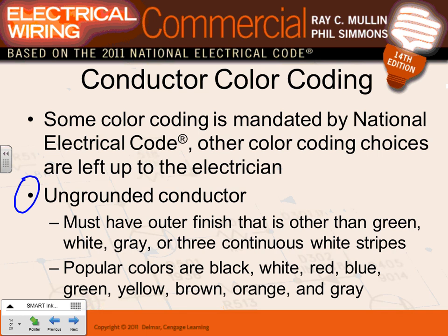Can you guys go to page 102, please? In your book, page 102. On the left-hand side, they give you the industry standard color coding for your system. So we have single phase 2-wire: black, white. 120/240 single phase in a conduit, 3-wire: black, white, and red. 208/120 three phase, 4-wire: black, white, red, blue. Everybody can see that? This is page 102 on the left-hand side.